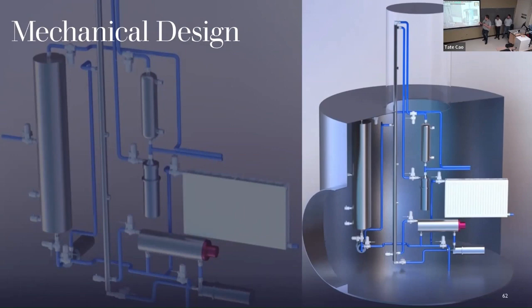So we didn't have to worry about that, but we had to worry a lot more about the corrosive material that's going to go through them. We made the column out of 6 different components because we had 6 different stages. As you could tell, it might be pretty hard to get it up into that stack unless those pieces could come apart. So this is something that could be assembled or disassembled in the enclosure.